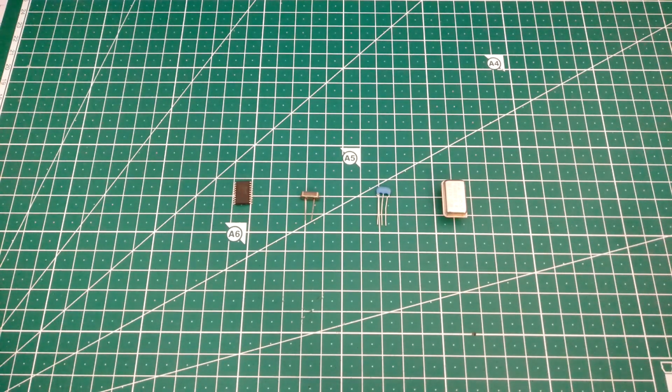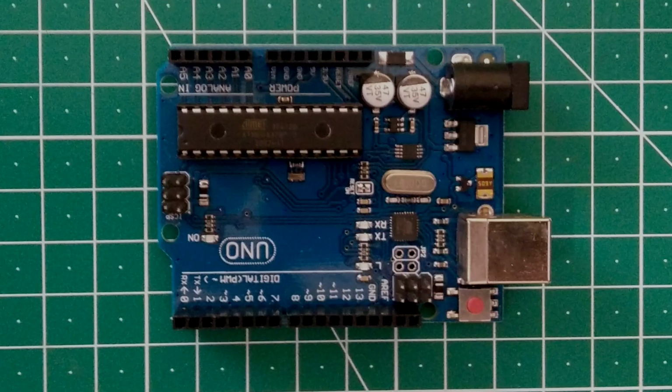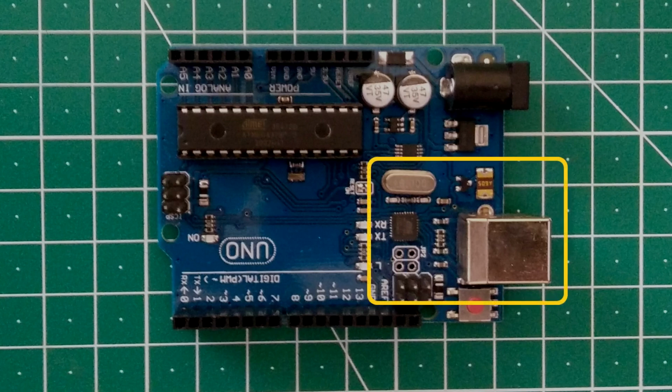So, crystals are more precise, but they do require the microcontroller to support them, and they are, of course, additional components and require themselves 2 load capacitors, so they do require additional components. However, you see them very often in things like Arduino boards exactly because, well, certain things do require the precision of a crystal in order for them to be used. Serial being a good example, USB being another one.